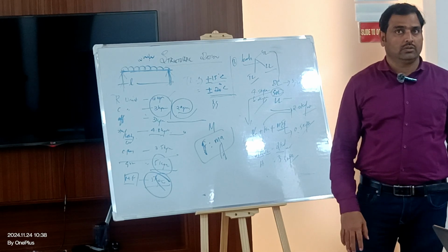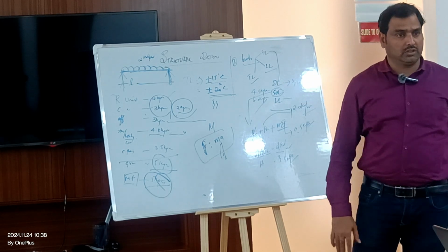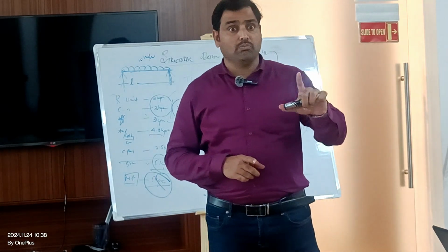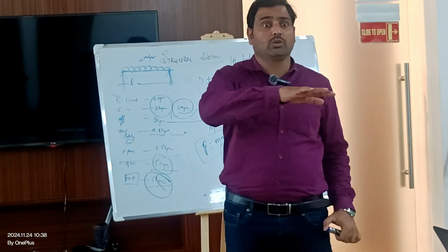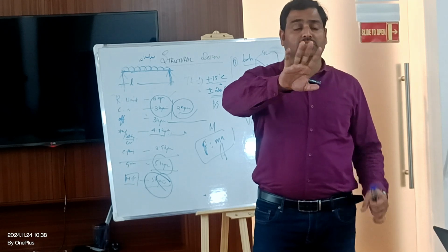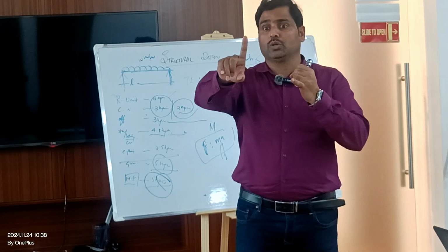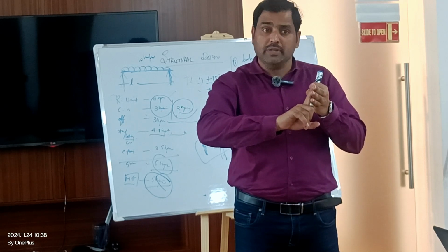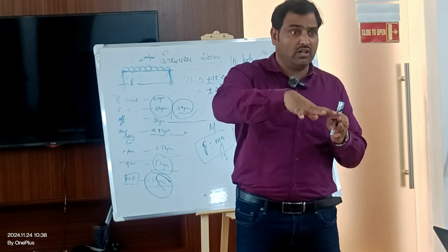What about the basement walls? From foundation to ground floor, what about the basement walls? Basement walls you don't need. I'm only talking about the slabs. You don't need to consider temperature for walls. You don't need to consider temperature for columns. You don't need to consider temperature for beams as well. I'm only talking about the shell, the slabs.